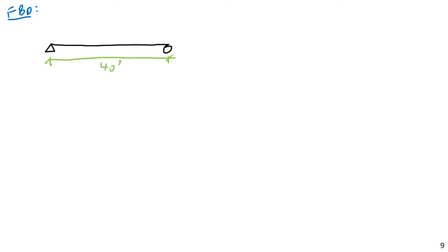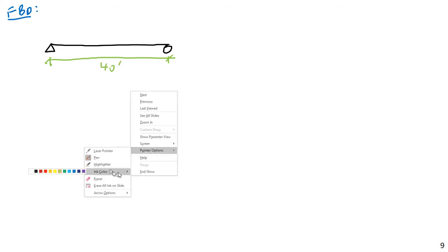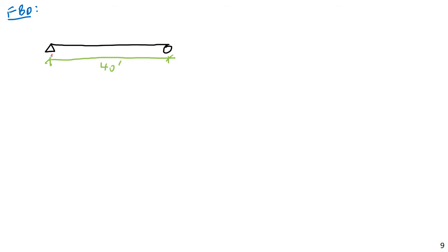So this is 40 feet long, and the load on here, the ultimate load, we're going to have an ultimate distributed load across the whole thing, uniform load, of 2.276 kips per foot. Now, where things really get interesting is if the load is not uniform. For example, say you had live loads that were applied as point loads and dead loads that were applied as trapezoidal distributed loads. Think about how that would work.